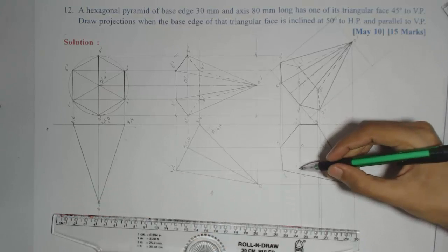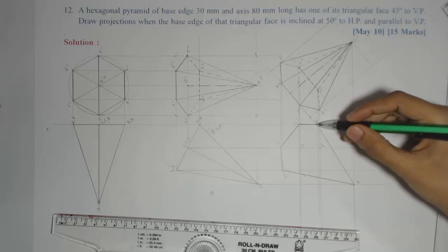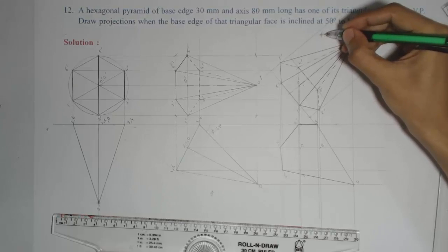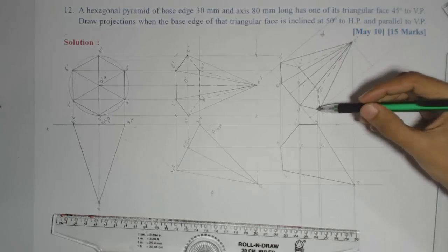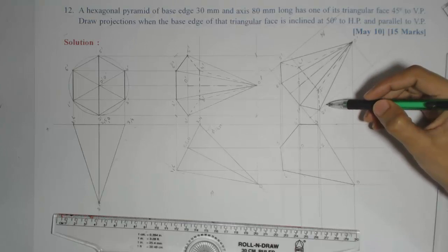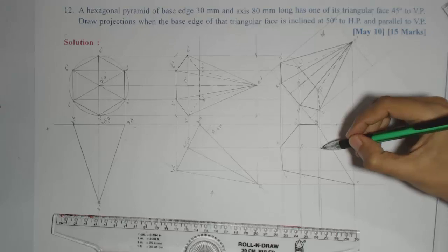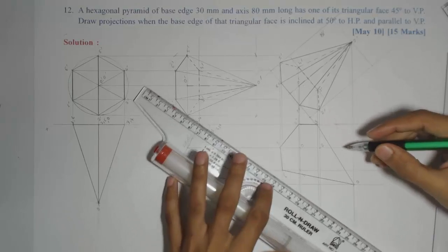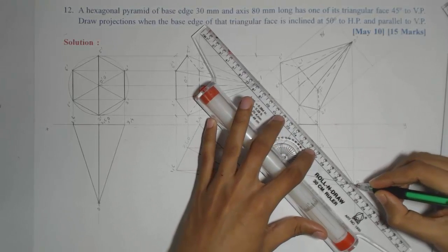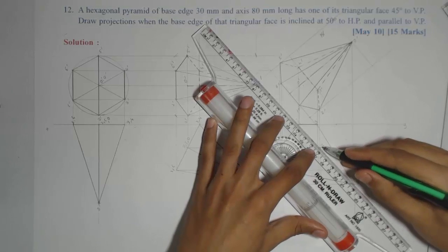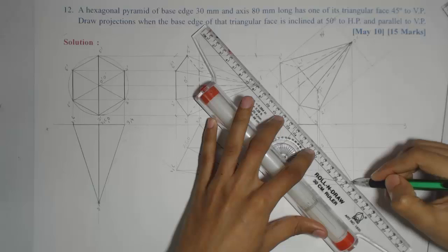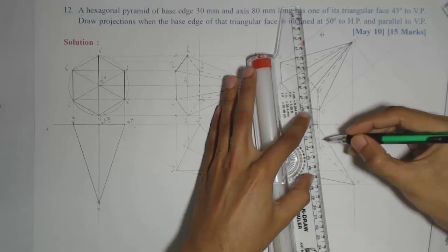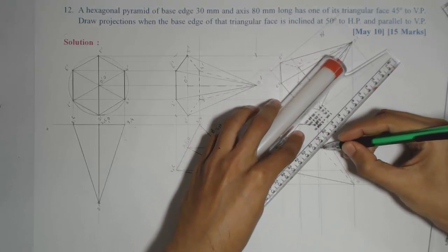Out of the remaining 3 base edges, 1, 6, 1, 2 and 2, 3, we'll see from observer point of view. Observer is lying here. So for observer, both 1 dash and 2 dash are farthest points. 2 dash is the farthest, so everything from 2 and 1 is also farthest. So everything from 1 and 2 will be dotted. So from each corner I am going to get 3 lines. First for point 2 I am getting 2 O, which is the slant edge. Then 2, 3, again the base edge dotted. Then 1, 2, again the base edge dotted.